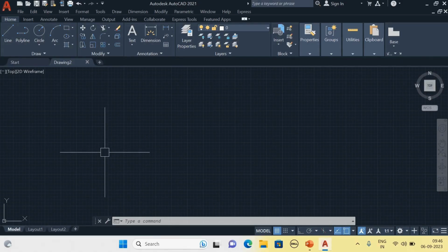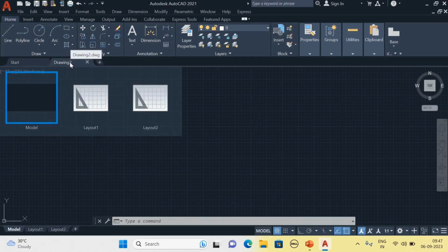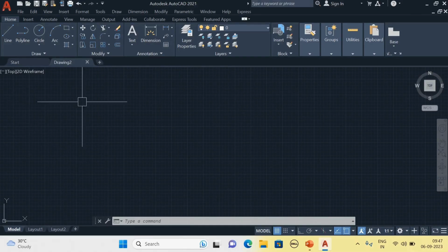After that, the next thing we have to discuss is the file tab. The file tab is shown here. The file tab consists of the current drawing file open on this screen. In your screen, the current drawing is open now. We can also type the filetab command in the command line if you want the file tab, to turn on the file tabs.